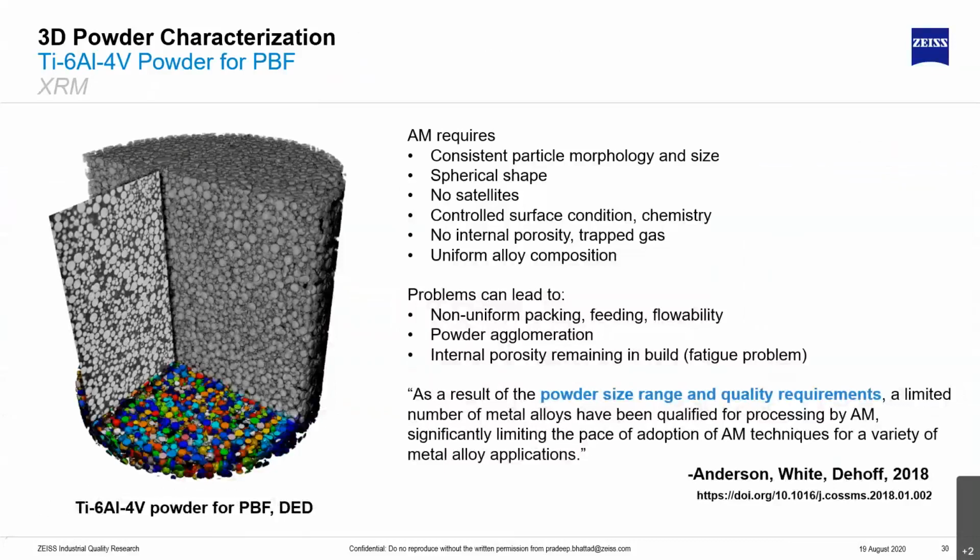What I would recommend, if you're looking at internal porosity of the powder, is using micro CT imaging. What we are using in this case is a micro CT tool, which not only gives me a full 3-dimensional image of the powder, but I'm able to sample a lot more powder particles and get much better statistical answers.